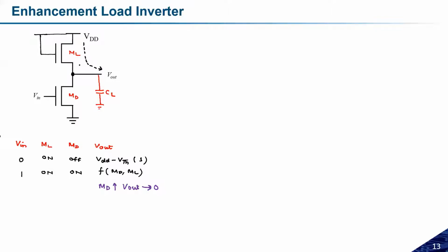But because I am transferring this high logic through this NMOS transistor, there will be some threshold voltage drop, because we have already studied the NMOS transistor cannot pass strong high. There will always be a threshold voltage drop. Okay. Yes, sir, got it. So the output we will receive is VDD minus VTH, which is close to the logic high. So this is the combination we are getting. And similarly for the second case. Okay, so this is the thing. Yes, sir, got it.